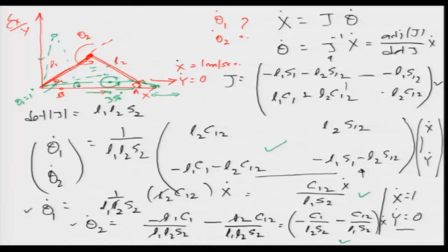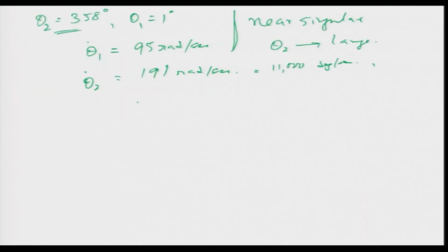So this gives us an example of a two-link manipulator and the importance of the Jacobian matrix, and how the Jacobian matrix can be used to determine singular positions, and also the relationship between the joint velocities and the end effector velocities. Now this is a physical system, right. So if the velocities are related in some way, joint velocity and end effector velocities, then the forces and torques would also be related, right. So if at the end effector we are applying a force here.